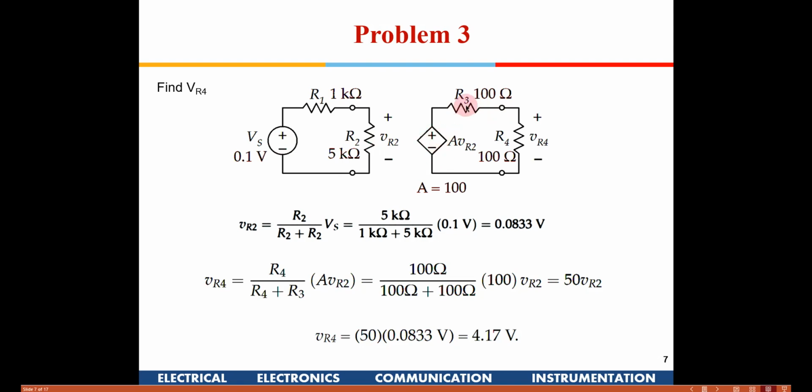Again there will be a series resistance. Because of these two practical resistances which come in series in both these sub-circuits, the gain is reduced to 41.7 rather than the full gain of 100.